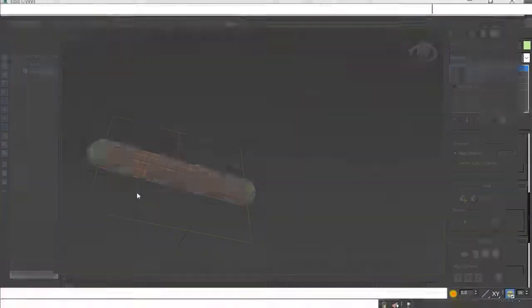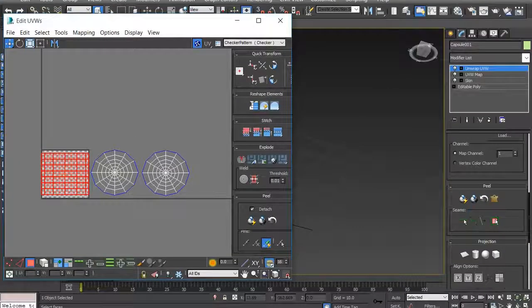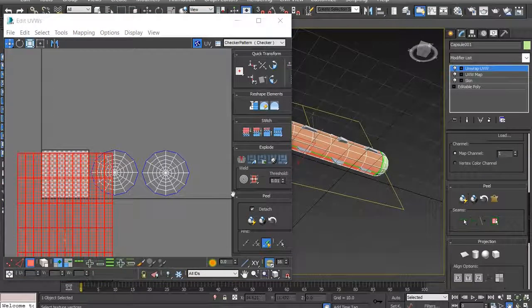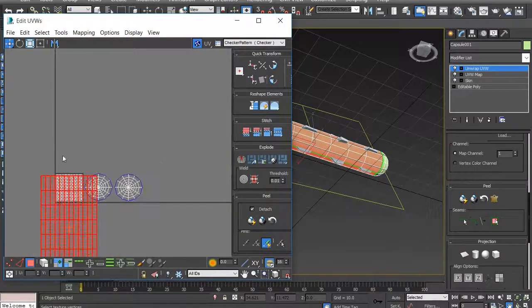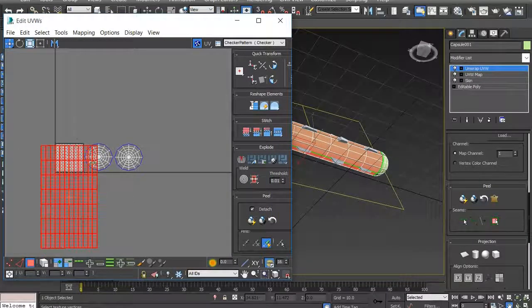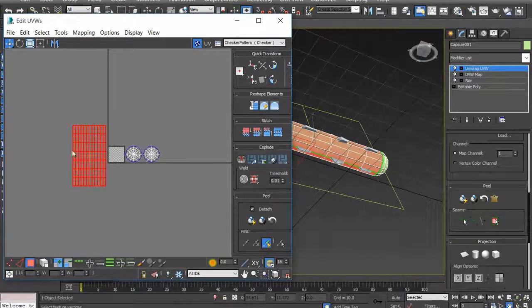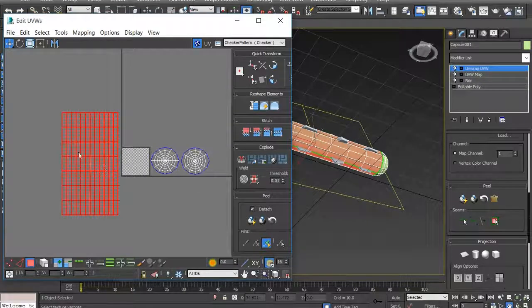Now we'll open our peel menu again, and just want to align things so you can see what happens. So there's our selection. We've selected everything over here, but we want it unwrapped. And so when we quick peel it now, it takes all of those, lays them out side by side in a much larger grid. And now we'll move those over here. Now the trick here is we need all of these shapes to be inside of this square, because this square represents the bitmap that we're going to use to apply a texture to all of these surfaces.